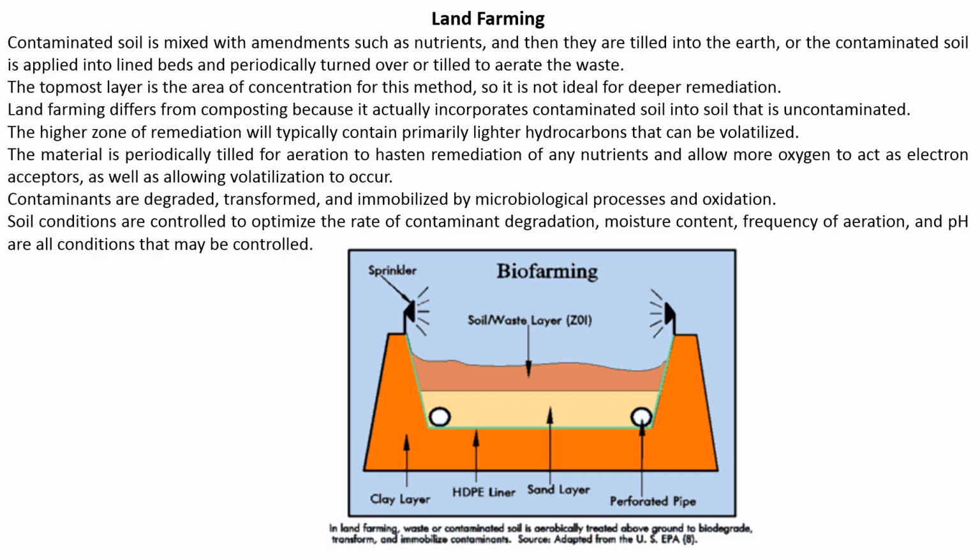Okay, so we are going to discuss what are the different techniques of environmental remediation that you can apply for both ex-situ and in-situ. So one of the techniques that can be applied on the polluted site or on the excavated contaminated soil is land farming, and it is very similar to biopiling, only that the HDPE layer is present, but what is not present is you don't have a polypropylene cover. So that is one major difference between land farming and biopiling.